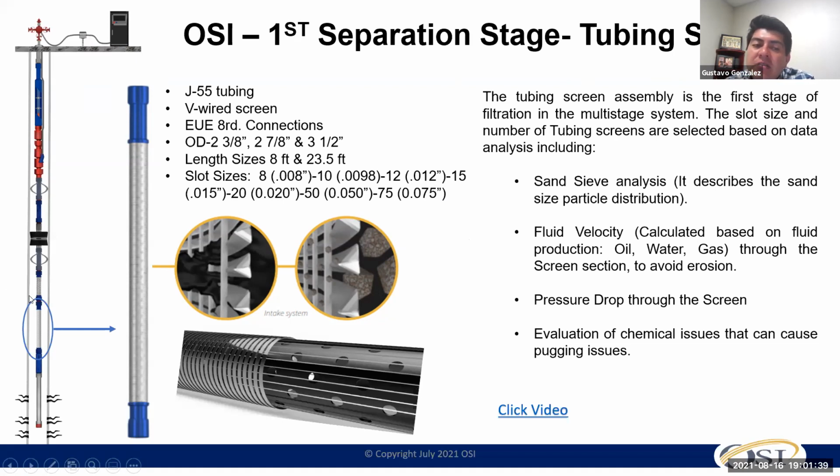And you know, the sand is not falling down whole, because it is still light enough that some portion is going to be suspended with the fluid, and another portion is going to be just agglutinated. And you're going to see more sand passing through the screen and hitting that screen over and over until you're breaking and losing that agglutination and you allow those particles to flow through. At that point, you're not plugging your screen, you're just regulating how much sand can actually pass through.